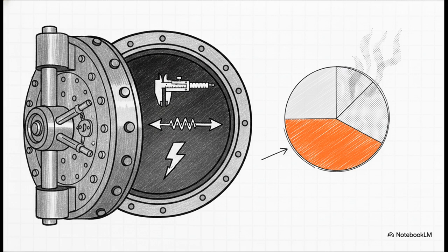But wait, here is a classic exam trap. Even at 100% modulation, where mu equals 1, your maximum efficiency tops out at only 33.3%. Think about that. That means a massive 66.7% of your total power is completely wasted transmitting the carrier wave, which contains 0 actual information. Crazy, right?